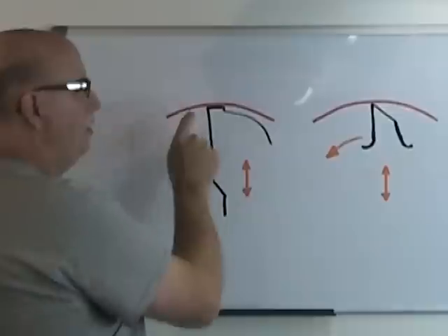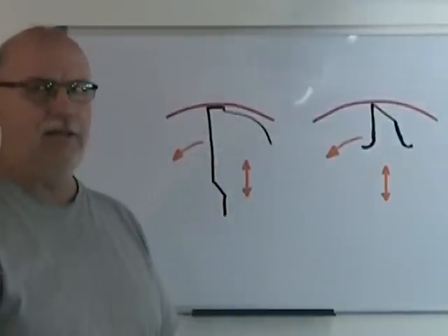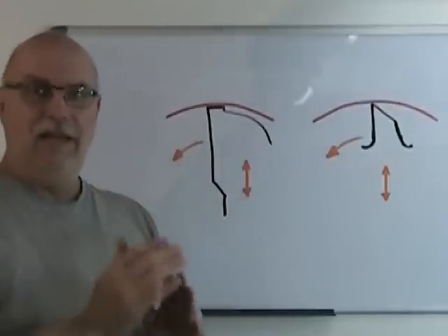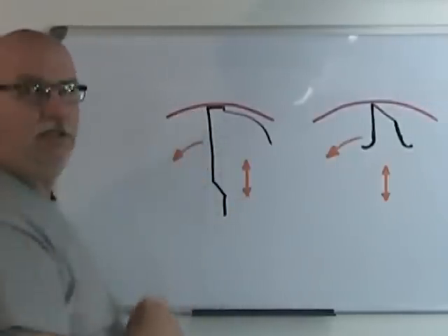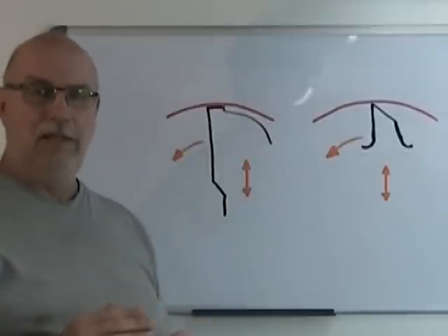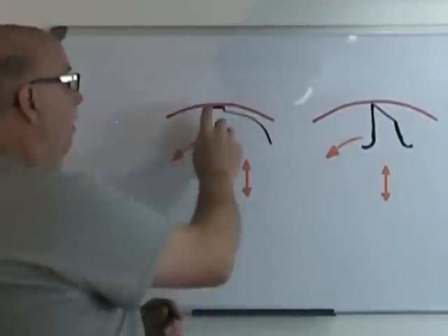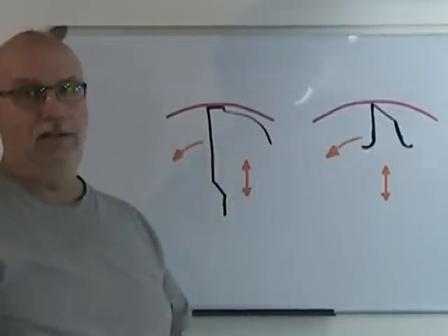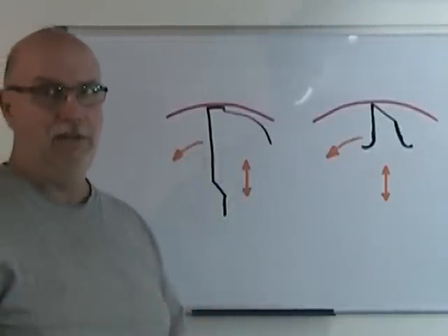So why do these margins have to be sharp if they're not a cutting edge? Well, they have to be sharp because if they were rounded out and did not have a sharp edge on them, chips would easily get stuck between the margin and the inside of the hole, and that would obviously jam everything in place.